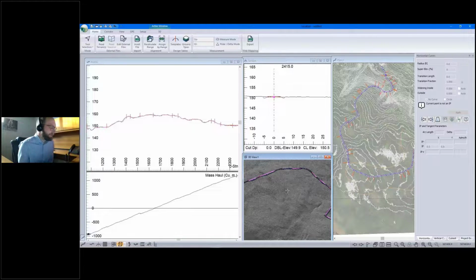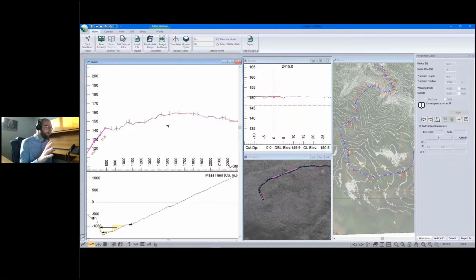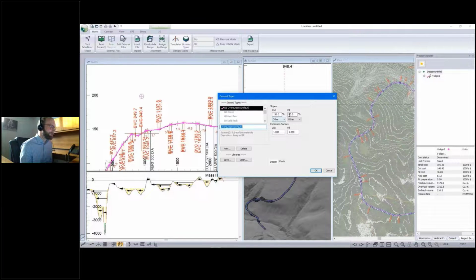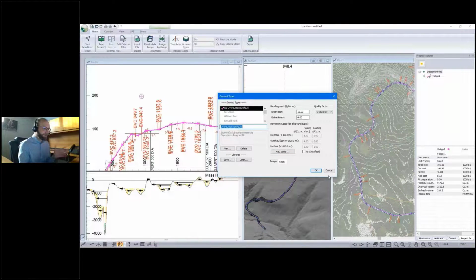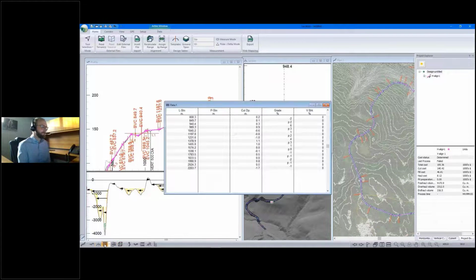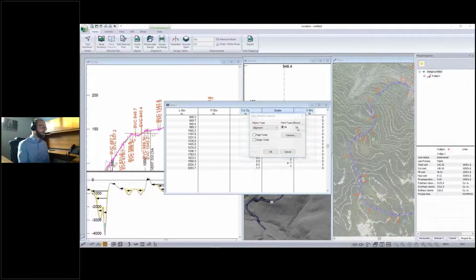Now with this, I could have done this earlier on, and usually if I'm designing not for a video, I do. I'll keep track of what's going on quantifiably. So right now I've got my ground types open, which has some costing information in that. So I can use our design time costing function to hit recalculate, and I can see in the bottom right panel there, it's telling me it's about $195,000 to build this road based off the geometry and the assumptions I've made for costs.